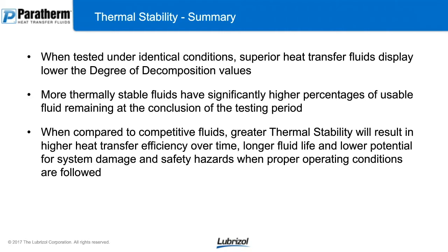So we need to make sure we pay special attention to that area and how we can maximize our performance there so that we don't prematurely degrade fluid. The higher the thermal stability of the fluid, the more efficient the fluid's going to be at transferring heat away from that pipe wall, and that's going to change your flow dynamic situation and give you better efficiency and lower energy that you would need to actually move that fluid.